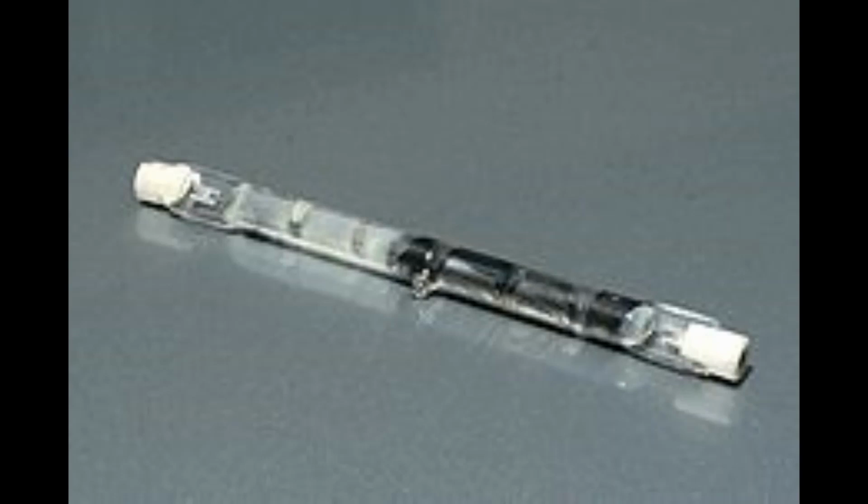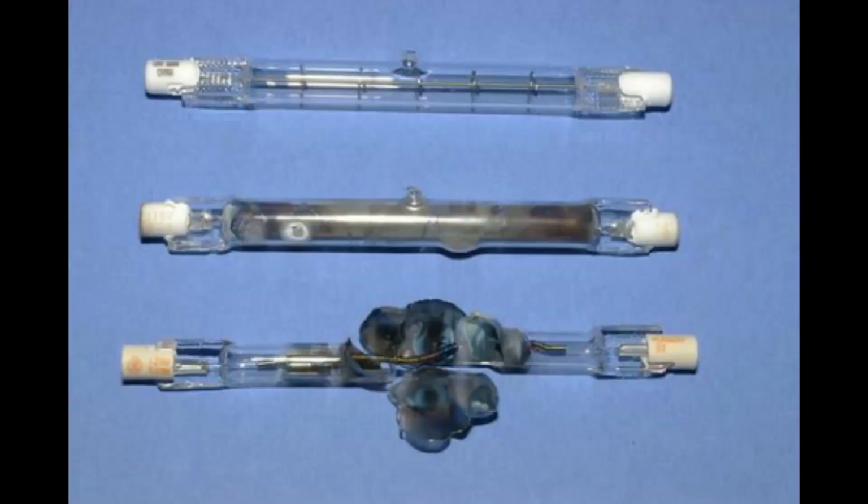When this is heated up to the extreme temperatures when it's in operation, it will degrade the glass structure, causing minimally a shortened lamp life and a burnout, or worse, an explosion of the lamp inside the instrument. You must be very careful in replacing these lamps, and do not touch the glass part at all.